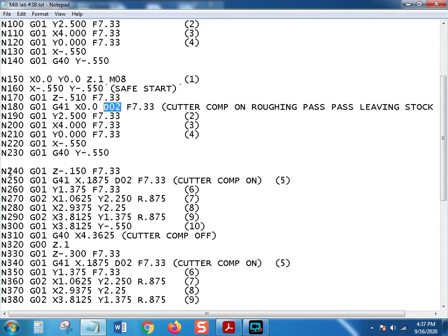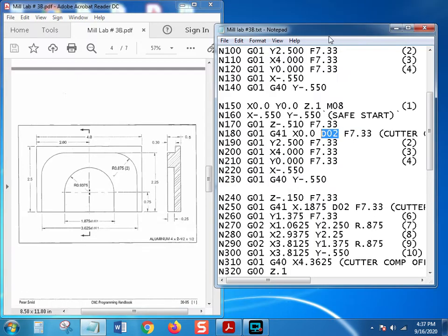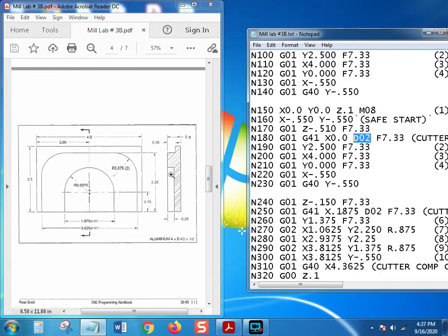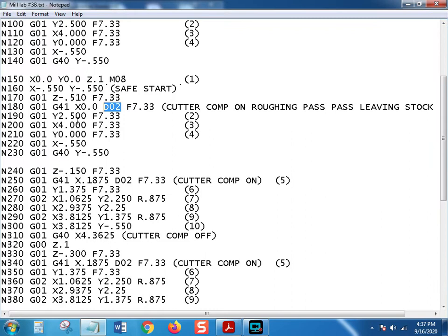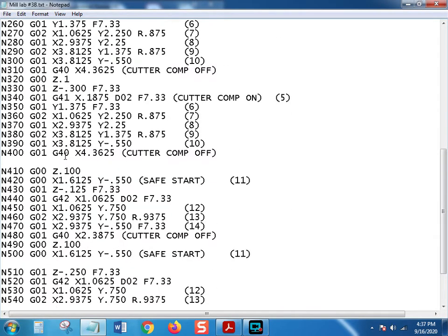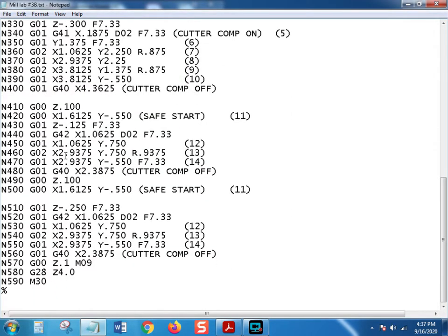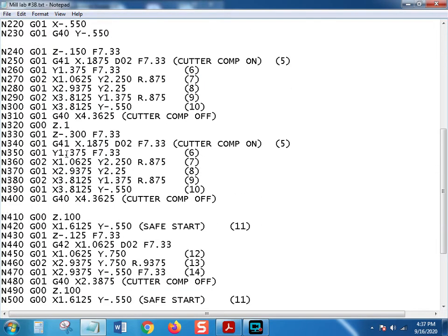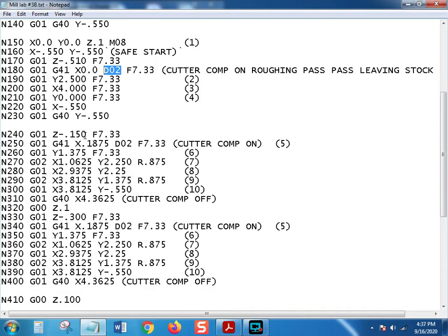This is where we actually did the pocket. Let me show you that again. I'm going to leave this alone. But we look at the pocket. It's 250 thousandths deep, right? Everybody see that? 250 thousandths? All right, we'll go back up and maximize this again. So at this one right here, now, if that's 250 thousandths, and I'm looking at that, I'm going to change this. Yeah, because I went down to Z150.